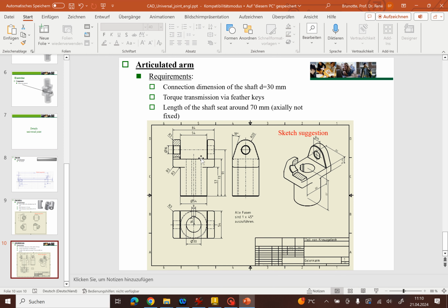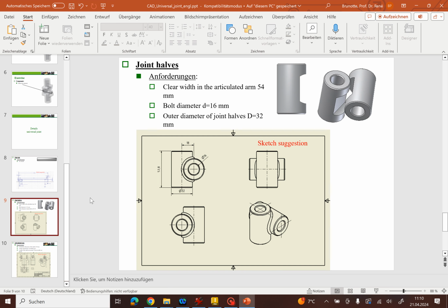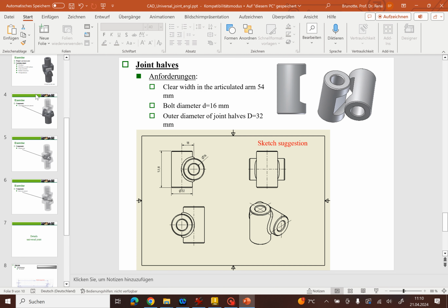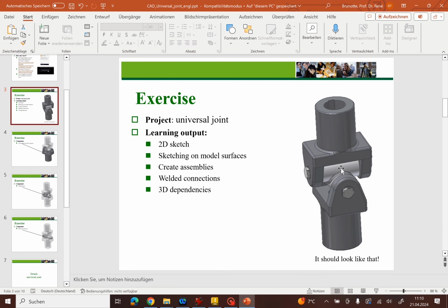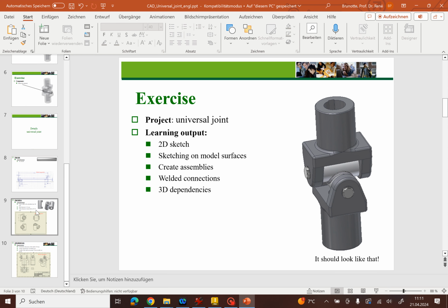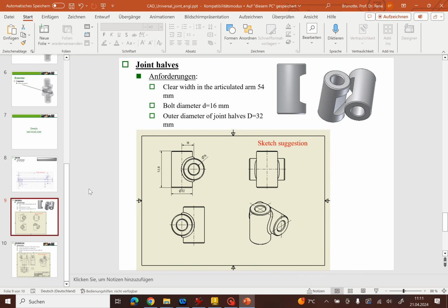And we want to make sure that our joint, what we create in the moment, has some space to move. And therefore our joint here is 0.2 smaller. Because this is later, you see that here. This is what we're creating now, and this is between or inside this arm. So there will be a short distance on this side and a short distance on this side. And in total, we make this joint 0.2 millimeters smaller.